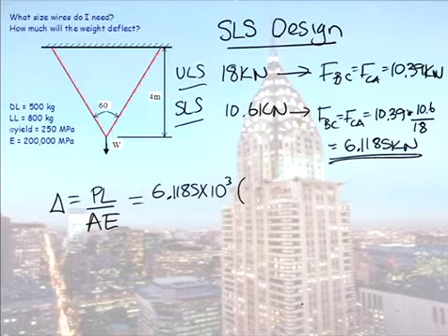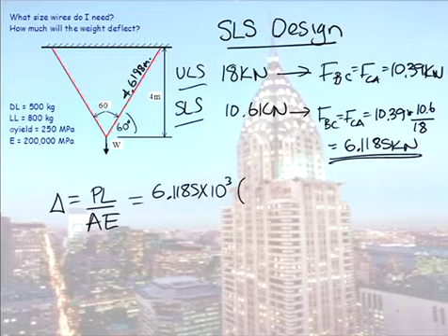The length of these cables, that's 60 degrees in there. That height in there is 4. So the length of this cable here is what? 4 on hypotenuse is sine. The length here works out to be 4.6188 metres. Yeah? Which is just the sine. Yes? Is everyone with me? Okay. So, we have our length in here.